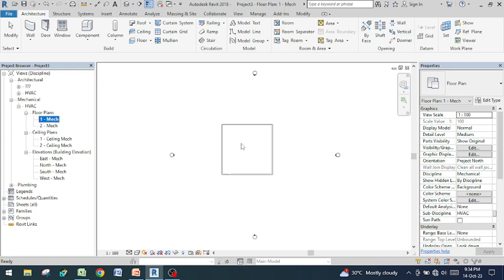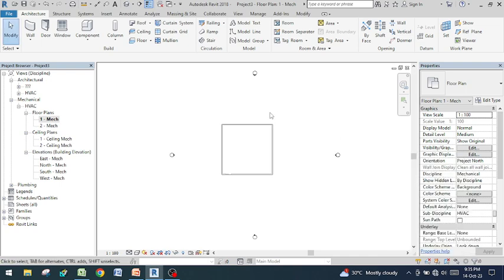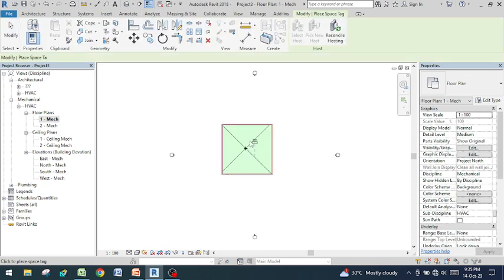That is, building information modeling provides the building simulation, meaning the energy analysis. If you create a heat load calculation here, if we are creating the heat load calculation in HAP software, we need to enter more options. The same HAP options you can find in analyze options. I just put a space here and apply the space tag.